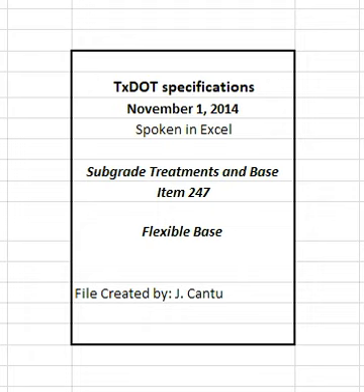Rework, recompact, and refinish material that fails to meet or that loses required moisture, density, stability, or finish requirements before the next course is placed or the project is accepted. Continue work until specification requirements are met. Perform the work at no additional expense to the department.